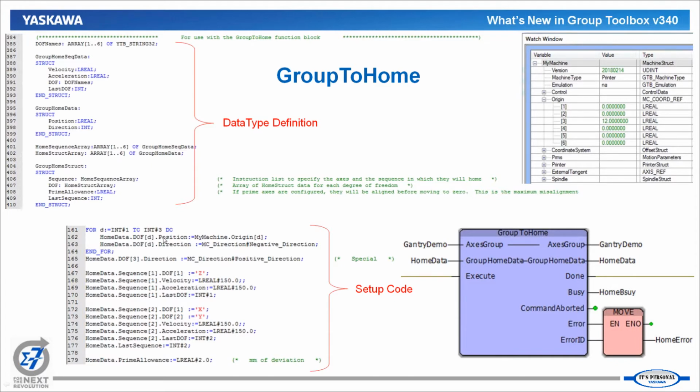So we're going to 0, 0, X and Y, and up to 12 on the z-axis. So those positions are being filled. And just for simplicity, all three of them are set to negative direction at first, even though we come back afterward and override the third one for the z-axis. We actually want it to go in a positive direction. So we specify the degrees of freedom by their string name, as you would see in the hardware configuration. So first off, the z goes up at the speed specified here, and once that's complete, the X and Y will go to their home positions.